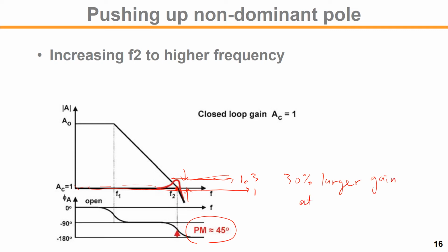Near the cutoff bandwidth frequency, right? So closed loop bandwidth is defined by the omega u of the open loop gain. Omega u of the loop gain actually determines the closed loop bandwidth. This means near FU of the loop gain. Okay. So our goal is how to push this F2 even further to higher frequency. You want to make this FU even higher frequency. Okay.